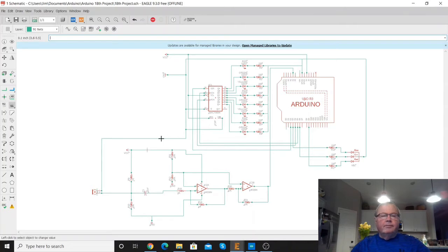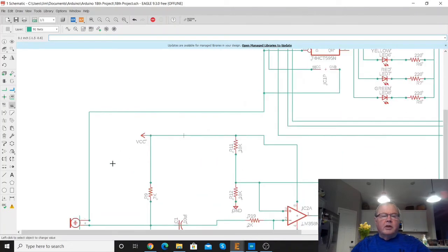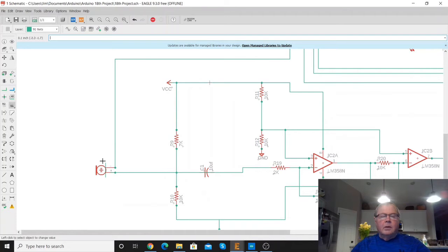So how do we do this? Well, we have obviously a microphone shown here, and that microphone is biased to about halfway, about 2.5 volts right here at this point, and then AC coupled into the input resistor of an OpAmp. And this OpAmp is tied to 2.5 volts as well on the positive pin, to get it to be equal to the input here. And how much amplification do we have?